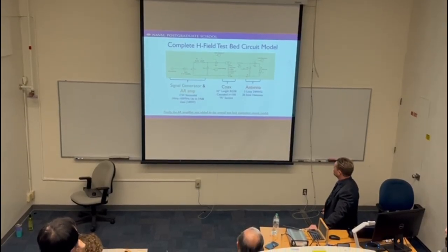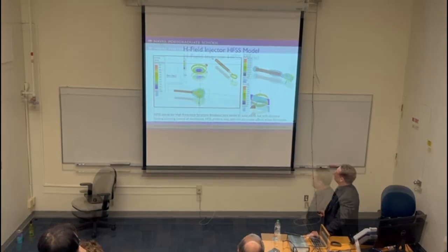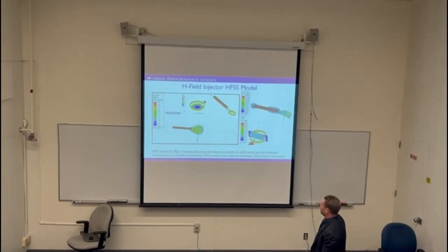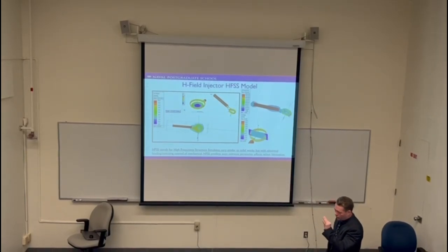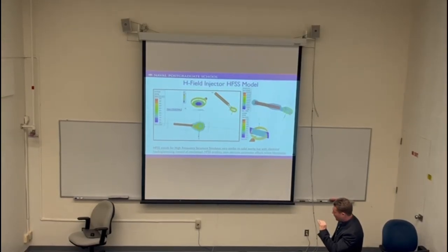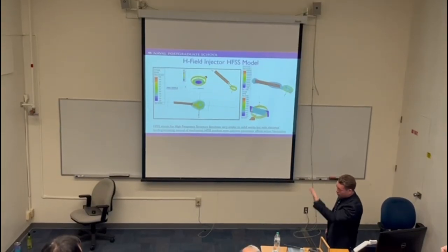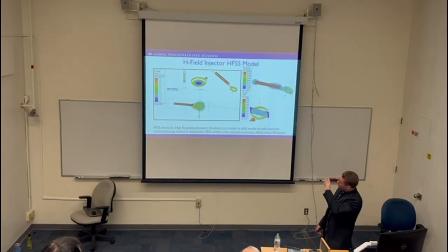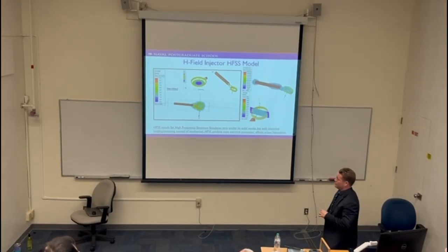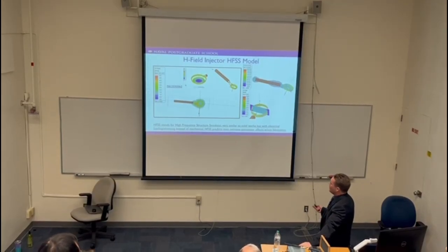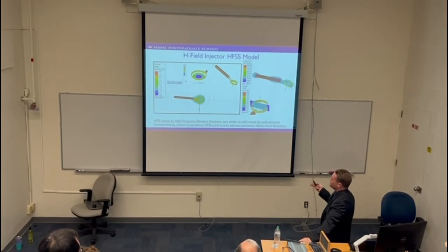And in the end, as you can see here, I got a cool little cartoon of an HFSS H-field injector that is built from 100% scratch. You literally start with a center conductor, then you build the polyethylene on it, then you build the outer jacket, the shield. The entire thing is made from scratch. All the dimensions, all the permeability, all of that goes into this modeling. It's extremely impressive, and it can tell you what H-field to expect depending on what you're injecting into the system. HFSS stands for High Frequency Structure Simulator.